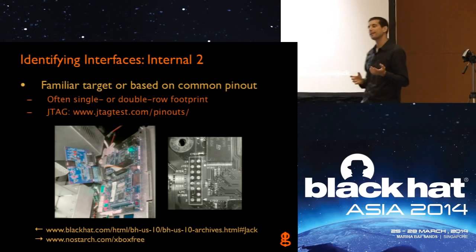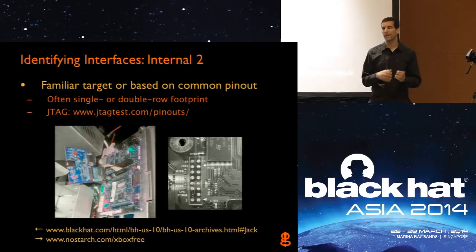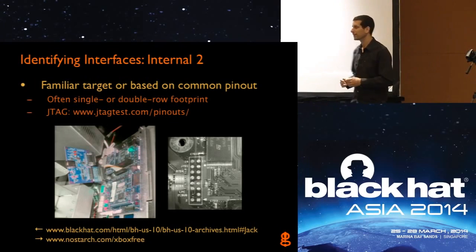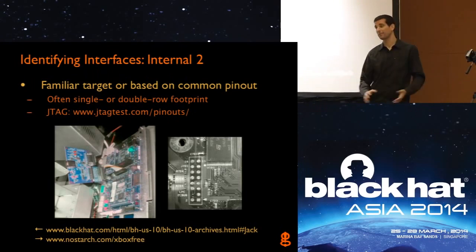It doesn't mean that the engineers are going to use those pinouts, but it makes their job easier, right? Because if they just use a standard pinout, then their standard development tools are going to work on it right away. They don't have to create some interface module to make it harder. So a lot of times we'll see just a standard interface that we can plug into with JTAG hardware, not even needing JTAGulator at all, because we already know the pinout. Plug in and go to town.